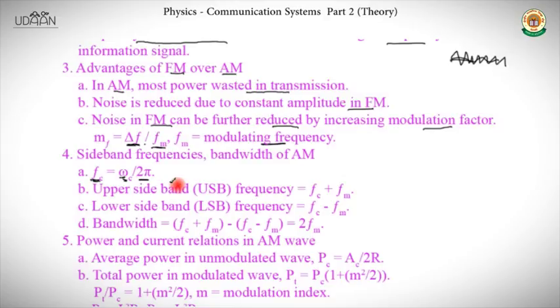So from there we get two expressions, and those two different terms have these frequencies: FC plus FM, which is the sum of the carrier frequency and the modulating frequency. In that topic I wrote it as omega c plus omega m, and omega c minus omega m. These two can be broken into FC plus FM and FC minus FM, just by converting the angular frequency. It is easily converted to the normal frequency.